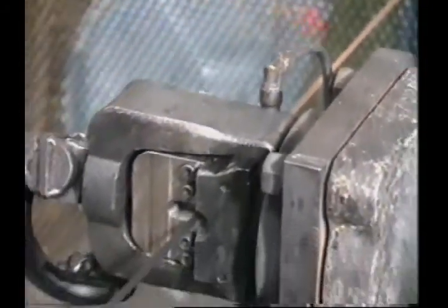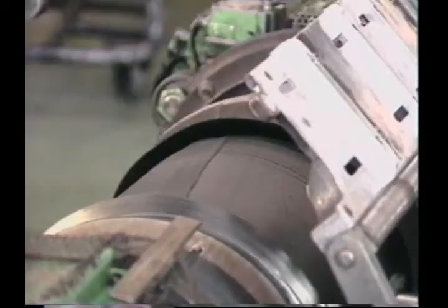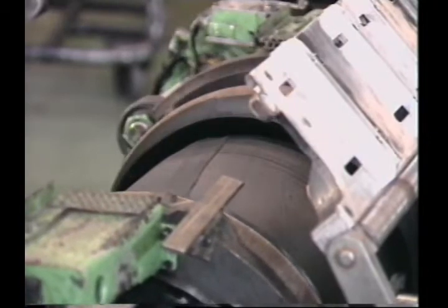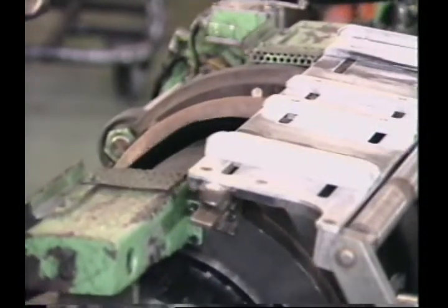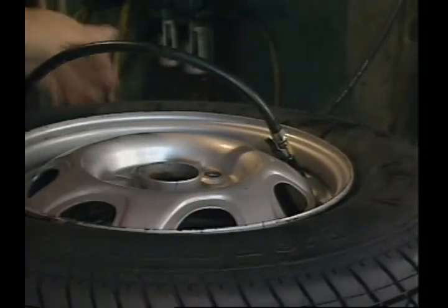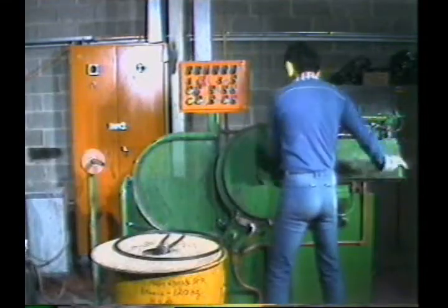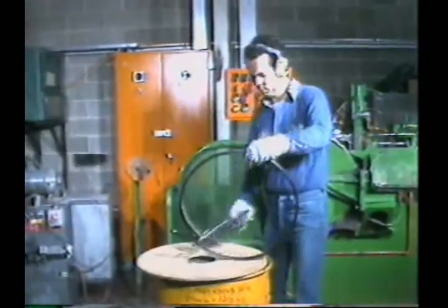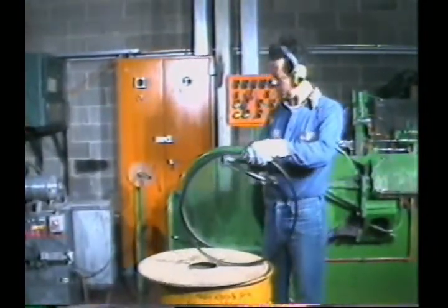The bead of the tire is made of a cord of high tensile steel coated with rubber. The end of the ply is wrapped around the bead, which is then wrapped in rubber to stop chafing of the plies and also to seal the bead against the rim. The length of the wire used for the bead determines the rim diameter of the tire. Belts that reinforce the tread area of the tire are mostly made of braided high tensile steel wire, but they can also be made of rayon or polyester.